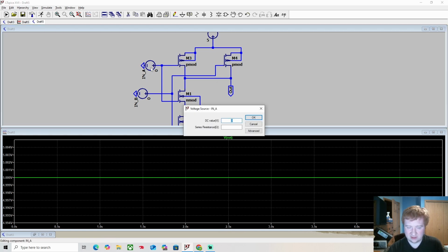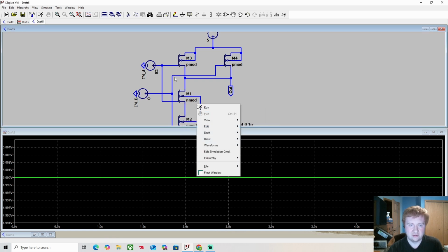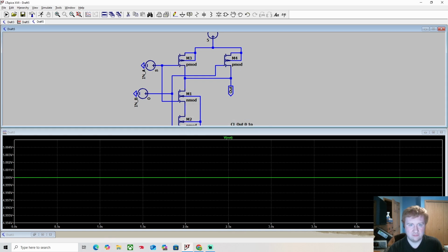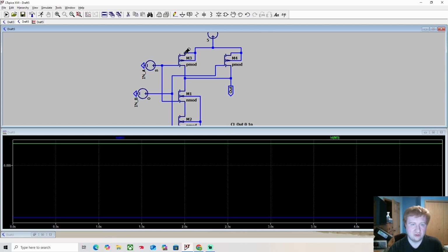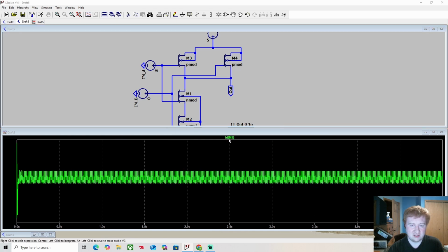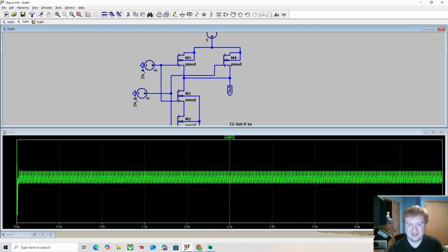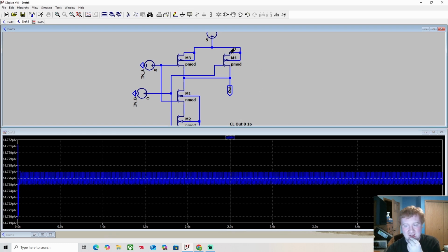If I were to switch these, one of the inputs, input A, to 5 volts, it's still going to be a 5 volt output, because this switch now opens because the gate is the same as the source. So through this we should see pretty much no current. I think this is, if I were to measure this, femtoamps, like that's nothing. Almost. Picoamps is a lot bigger.